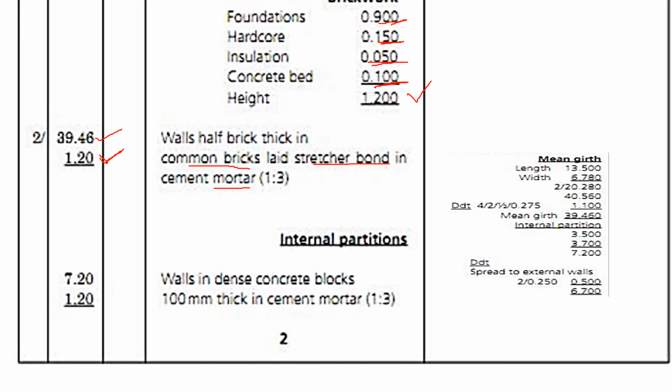Remember, in the external walls, we have a double wall and we have a gap at the center. It's a double wall. So we shall multiply by 2 for the external and for the internal. So the area will be times 2 because we have the area for the outer wall and the area for the inner wall because it's a double wall.